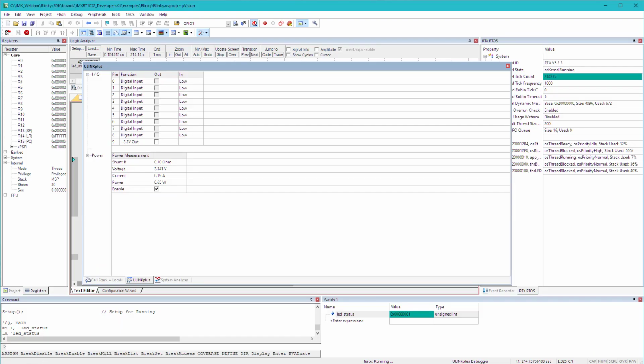Now let's get back to our application. Here in the ULINKplus window, I can configure and monitor the pin status. So our pin 0 is already configured correctly, and if I connect the wire on the board, you'll see how its status is shown here. In the same manner, the analog pins can be used. You can type the target value for the output or observe the measured value on the input. It is 0 here, as I have really nothing connected to this pin in my setup.